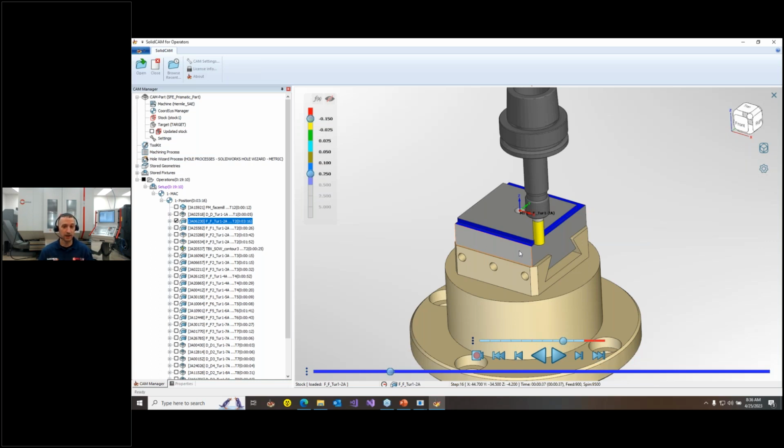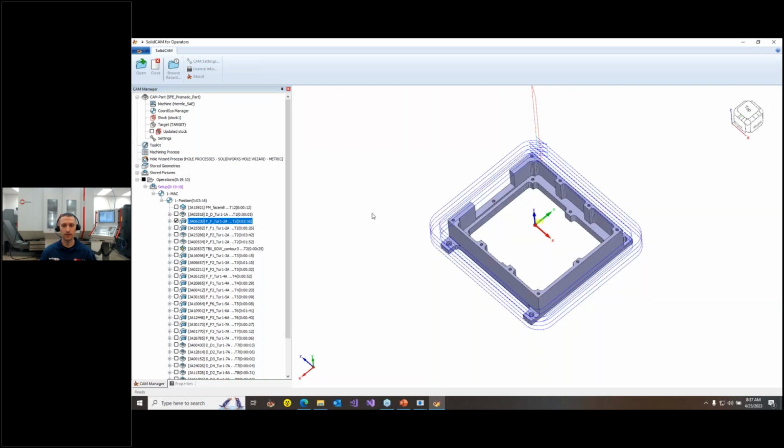And I know from my side, I would love as a CAM programmer if my operator said, hey, operation number 3 cuts around the outside. I saw you only did one pass. I tried to make it 2 passes, but it cuts air on the side. Could you modify that? It's just such a nicer conversation than saying, yeah, we left some material in the corners and you need to go do something about it. So I like this idea that CAM and the shop floor guys running the machine have tighter communication.